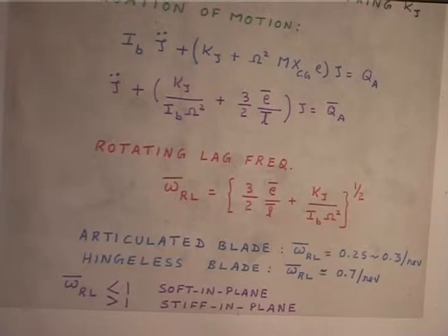Isolated lag is fine, that means just pure lag motion is stable, because the damping is purely aerodynamic damping. In this case, we have not put any external damper there. It is only drag force. In the case of flap motion, it is a lift force that provides the damping.